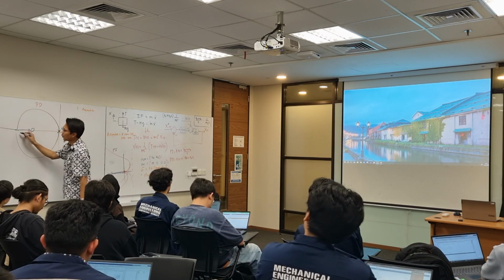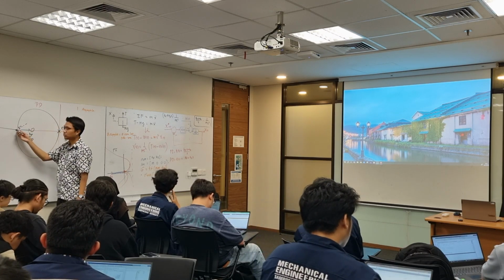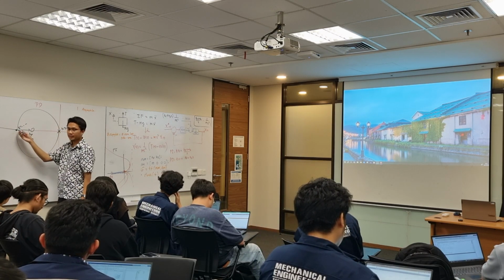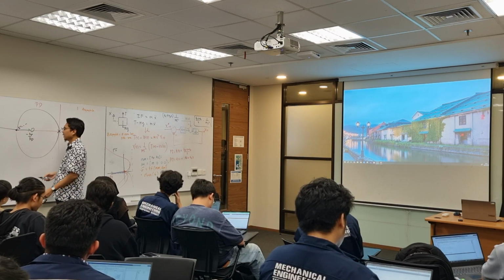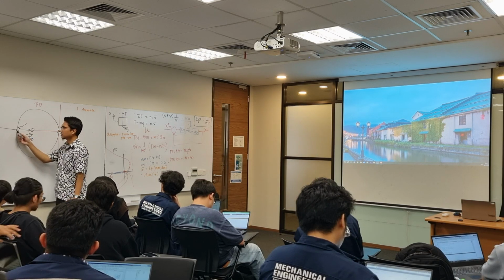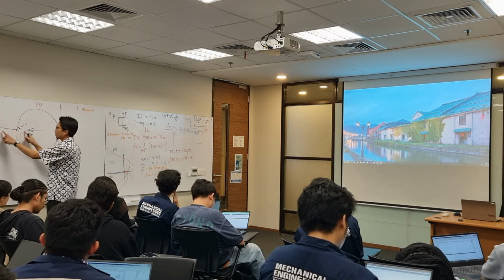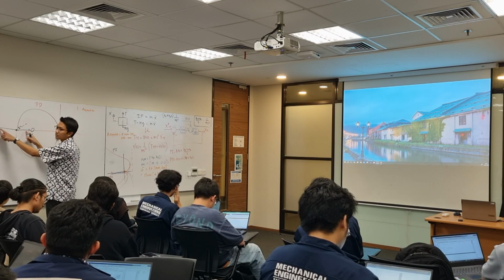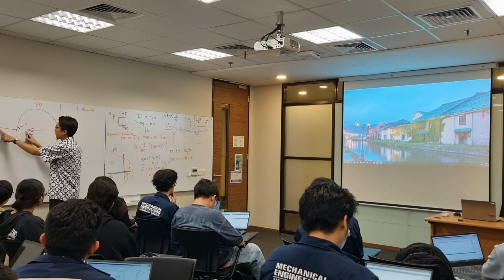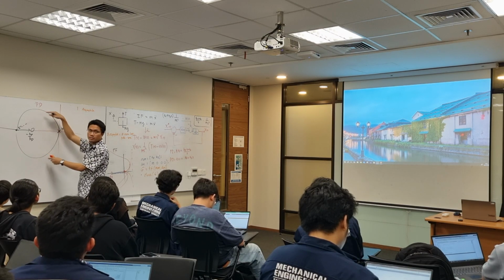Okay, and when you are reaching here, for some K your system is critically damped. You increase your K again, one closed loop pole goes to the right, the other one goes to the left. Then you can get your system to be over damped in here. Okay, if your system is here, then it is under damped.